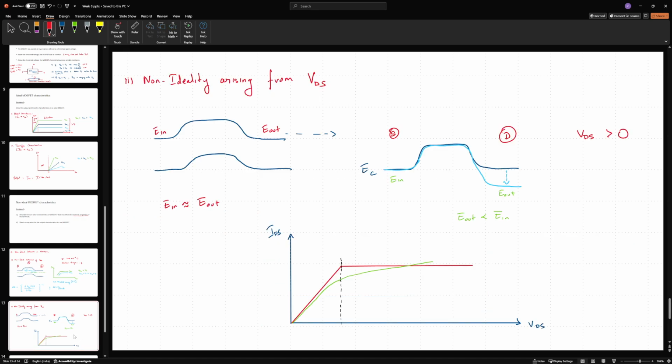So first and foremost, linearity is destroyed, and then saturation is no longer saturation. The current still keeps increasing. So this notion of where this barrier effectively is lowered, like this energy barrier, there is a lowering of the energy barrier. So this quantity is known as DIBL, and in fact at higher and higher voltages, even this point will start lowering.